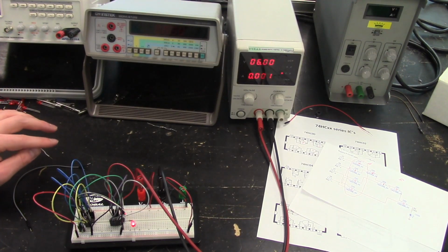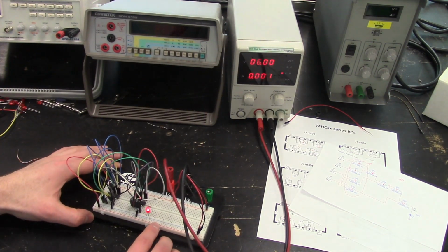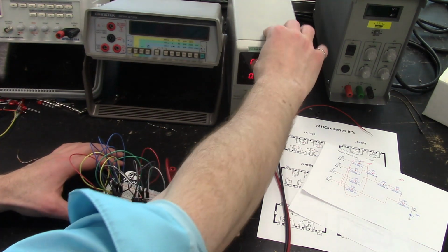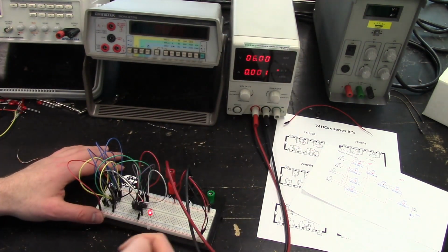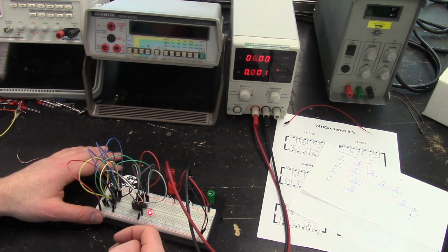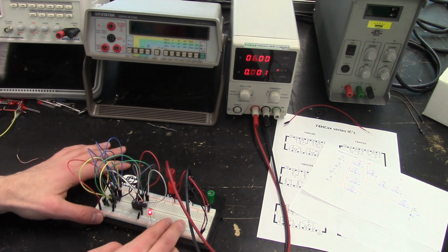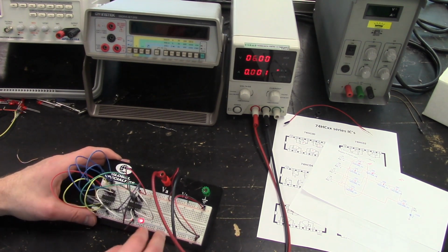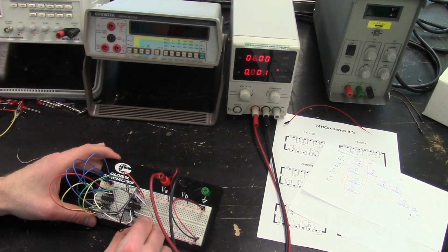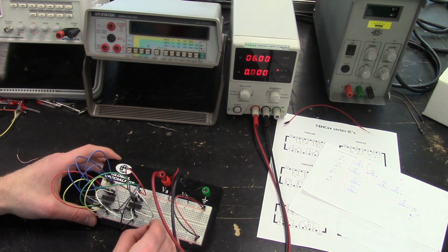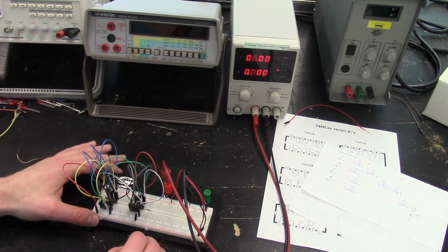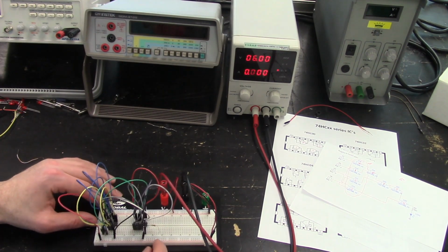So another verification thing that we could use is right now when the LED is on, you notice according to this box, we're drawing a really small amount of current. I'm not sure if I actually believe this. So this says that we're only drawing 1 milliamp, and that's probably not enough to make this on as bright as it is. Still, if we disconnect the LED completely, it drops down to 0. I'm not sure I believe that either.